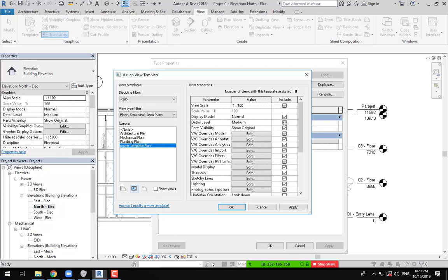Okay? If you check the box here in any parameter from this table, it will be activated through the Power Template Plan. But if you uncheck this box, it will be unactivated and you can use it from outside here. Okay? So if I uncheck the box for the Display Model Detail Level, I can operate and use this option from here.